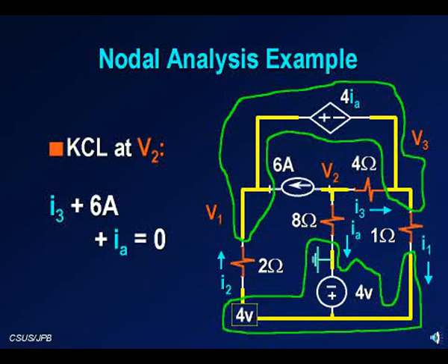You will note that I do my KCL equations in terms of currents. This is to avoid combining both KCL and Ohm's law, which often leads to sign errors on the part of students. In many textbooks, you see essentially the authors doing both KCL and Ohm's law at once. It's perfectly acceptable, but it's unlikely you're going to get it right over and over again. So I'm going to strongly suggest anytime you write a KCL equation, do it in terms of current, and then we'll do Ohm's law and then put them in and collect terms.